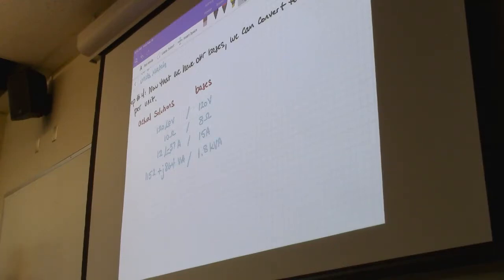And that's the one place where you can have a little bit of leeway there. If it defines it, normally they'll call... well, they may refer to the power base in watts or volt amps, but you can use either way in order to make the units cancel out. Technically, they should never define the base in watts. It should always be in volt amps, because watts is equivalent to volt amps anyway. And then we get our per unit values. Sorry, per unit values. See, even I...